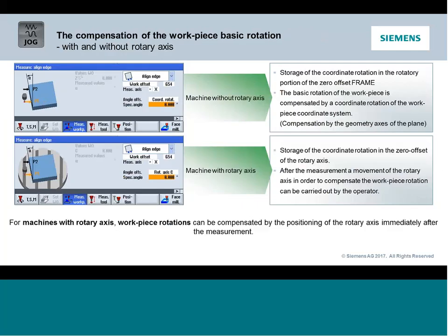Okay, now in the nature of our cycles being very adaptive, you can even start to use what would typically be thought of as an advanced cycle for maybe a 5-axis machine or a machine that has rotaries. Well, the system has the ability of still utilizing these functionalities with or without the rotaries. So things like align edge, which allow me to pick 2 points and figure out where my part is skewed.